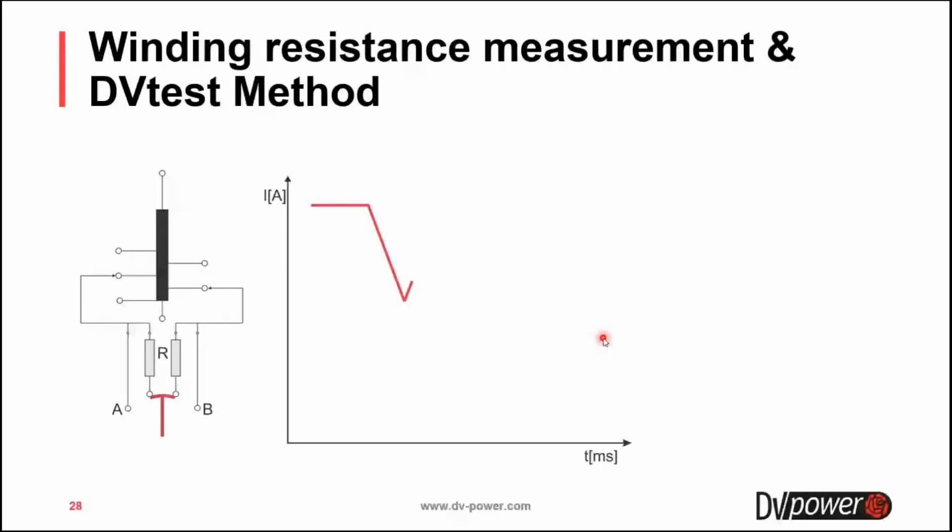Current will rise a little. After that, again one resistor stays in the current path. Current will drop down. After that, when the moving contact goes through point B, current will be stabilized at the new value of the static resistance of that position.